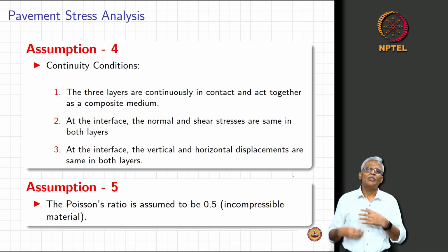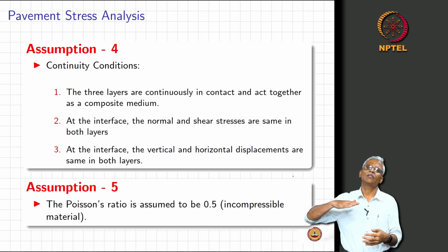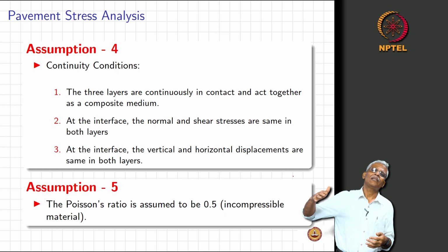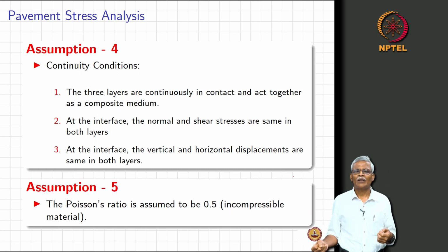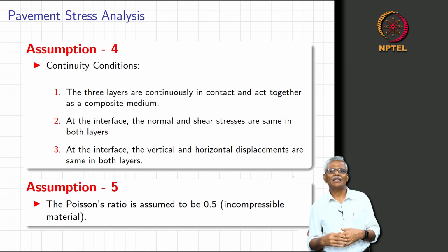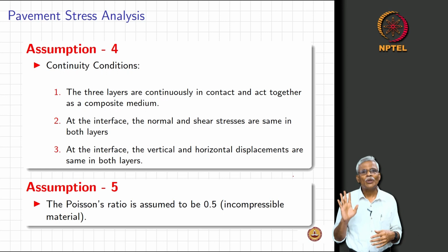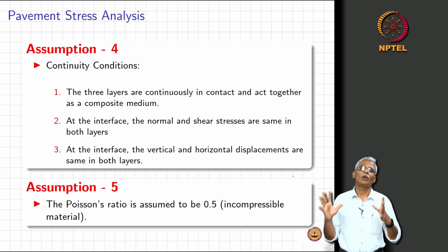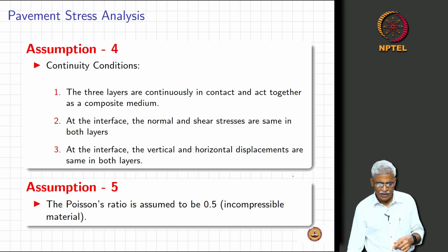So, this is a good feeling, and there is also some kind of cleaning of the surface, ensuring that the surface is clean, and the moisture does not play a critical role and all those things. So, other than that, the prime coat and tack coat do not have any structural role. They have more of a functional role. Okay. So, that is what you need to really understand.